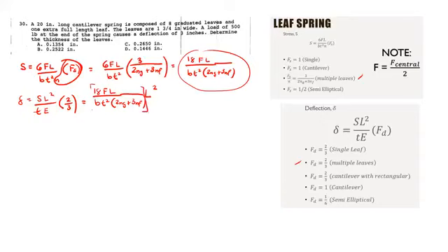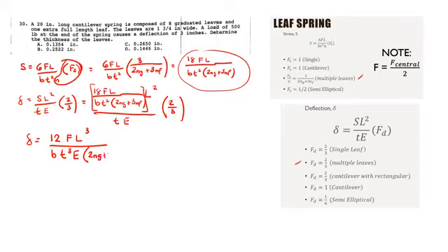So, times length squared divided by TE times 2/3. When we simplify that, 18 times 2 is 36, divided by 3 is 12. So 12 FL cube. Correction to our formula from earlier: 12 FL cube divided by B, T cube E, then 2NG plus 3NF.